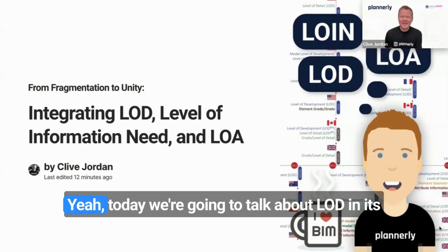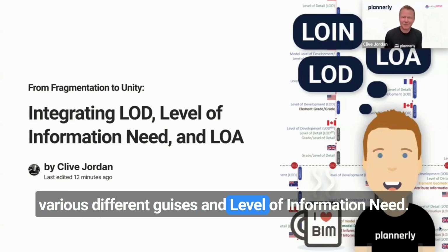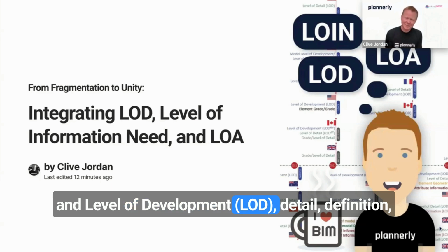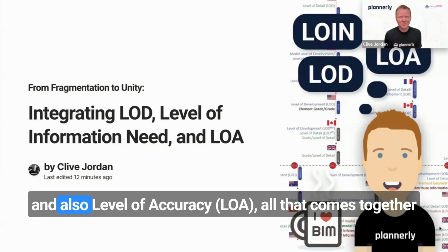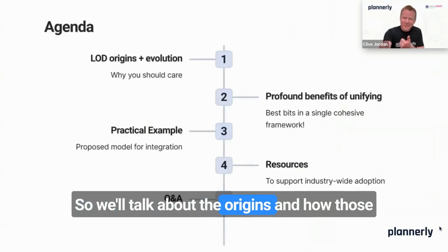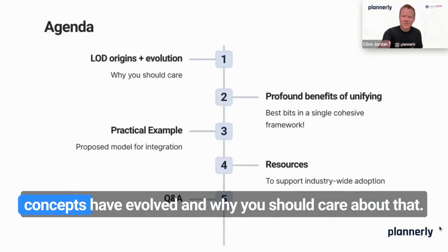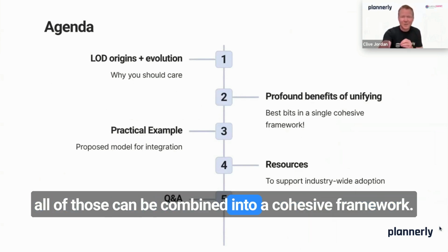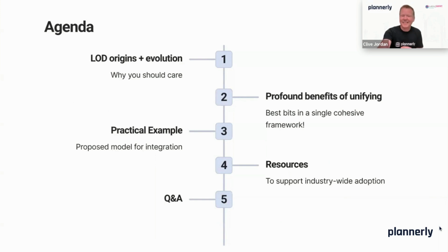Hey, everyone. Today we're going to talk about LOD in its various guises and level of information need, and how that 17412 and the ISO 19650 and level of development, detail, definition, and also level of accuracy, all come together to hopefully be simplified and make some sense. We'll talk about the origins, how those concepts have evolved and why you should care. We'll talk about the benefits of each piece, and then how all of those can be combined into a cohesive framework.